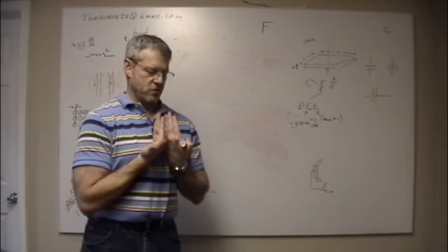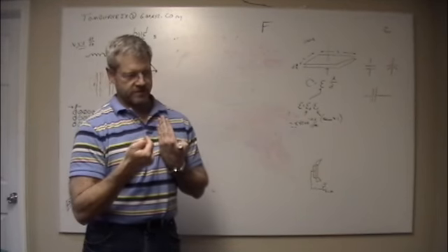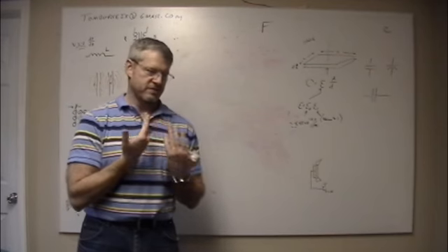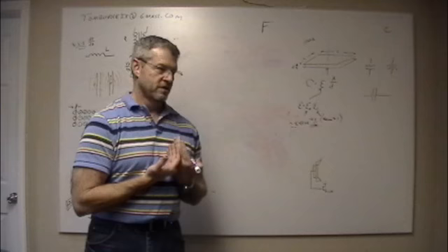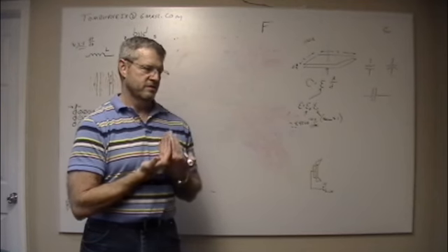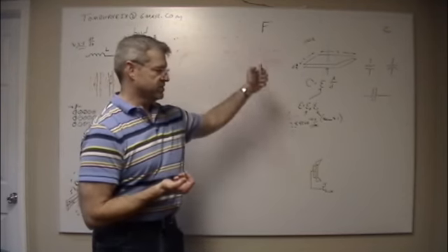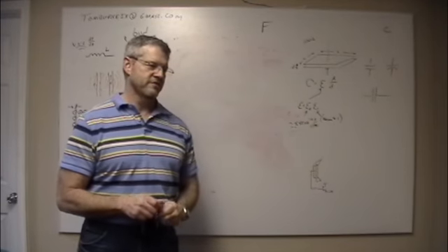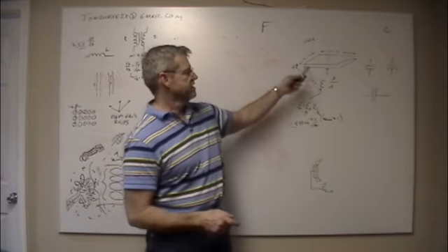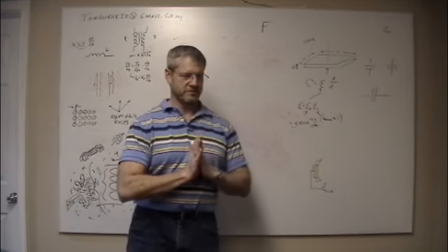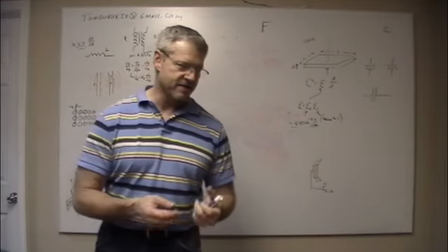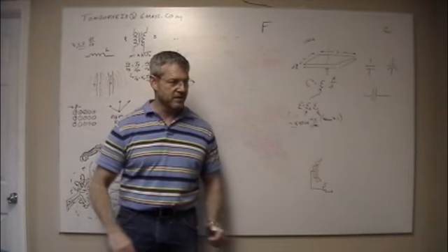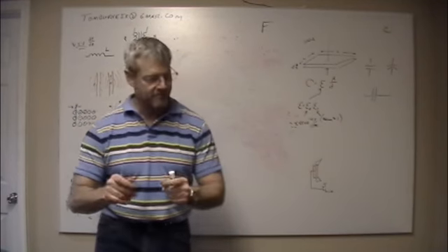If you're in a vacuum, there's nothing to prevent an electron from jumping across, other than just the fact that there's nothing there. As you get different substances in there that can change, heavy insulators can make epsilon go up. But where your biggest bang for the buck is, is either area of the plates or getting the plates really close together. An old style Mylar capacitor is literally 2 pieces of tin foil with a piece of Mylar in the middle of it and another Mylar on top, and they roll them up.